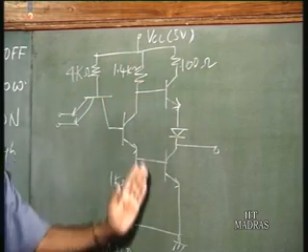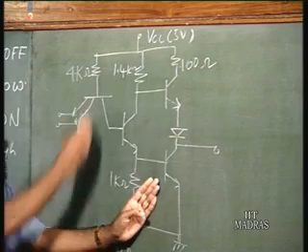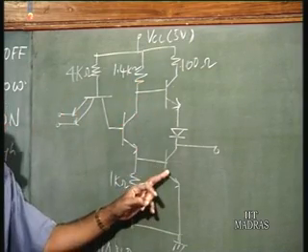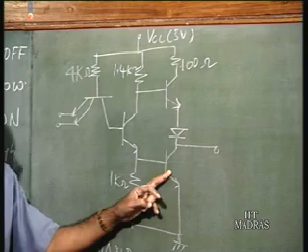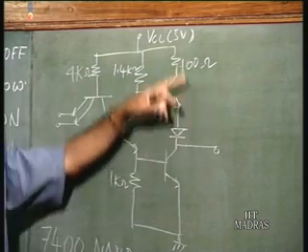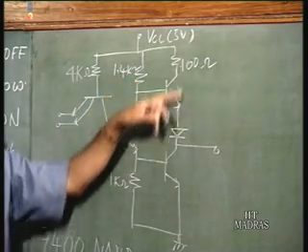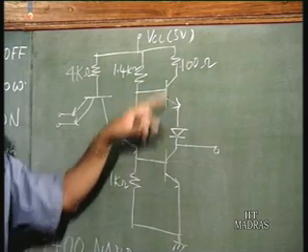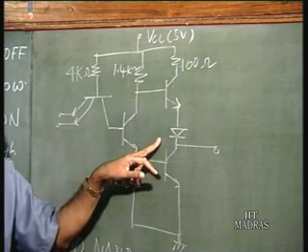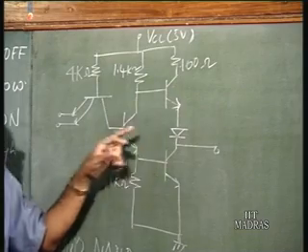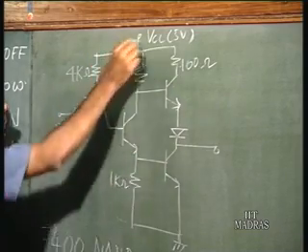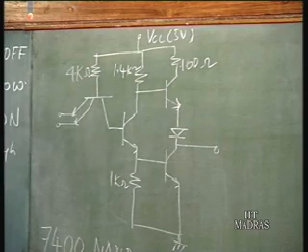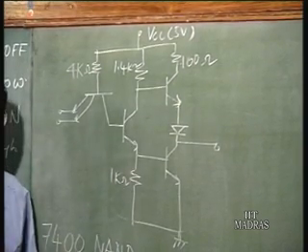This is the well-known circuit, in which you see that the resistance has been replaced. This is the output side. This is the same input side as previously. This is the output side, and this is the output transistor, the pull down transistor, which is still there. In the pull up side, you have these many components now. I shall come to why you require all of them. The pull up side is replaced, and you have a circuitry here consisting of one transistor and two resistances. This is what is called the phase splitter.